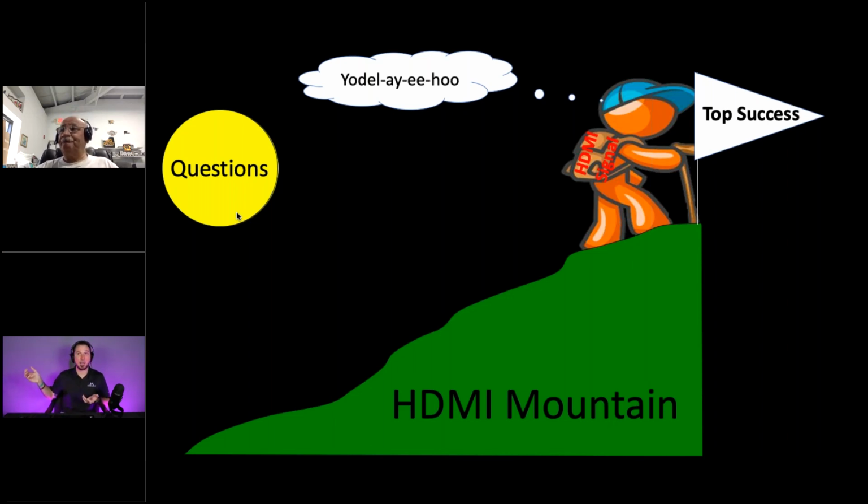I mean, that's right at an hour. Very valuable information. I think the big takeaways here are make sure the cable's plugged all the way in, so you get your hot plug and you get your 5 volt. That's going to be one of the big ones. The 5 volt seems to be what breaks a lot of things because we don't get DDC data.